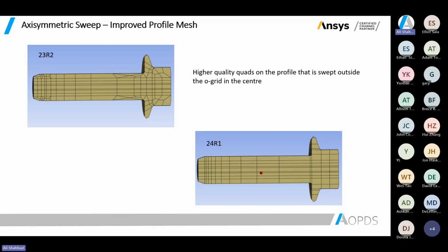If you see there are a lot of options that are on program controlled, or on automatic, automatic means that there is a default option selected by Ansys, and those default options sometimes change. And if you load the same model into the newer version, or even an older version, because the program controlled options could change in some cases, then your results could change.